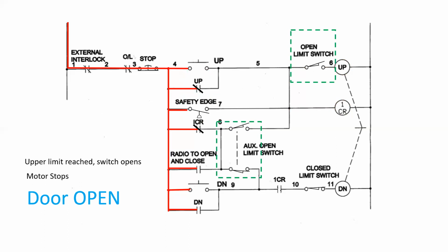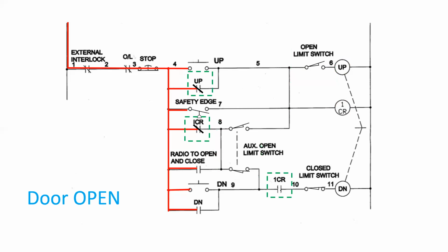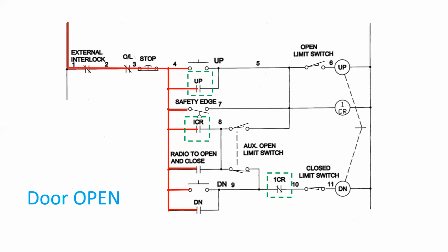So knowing what happens with all of these different pilot devices is extremely important. It's extremely important to be able to follow through a schematic for the full duration of its operation. And you need to be aware not only of how the system should operate, but also what the state of the different pilot devices will be due to their physical interaction in the system in the physical world.